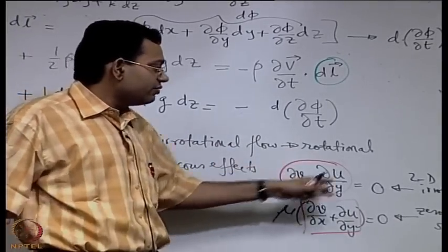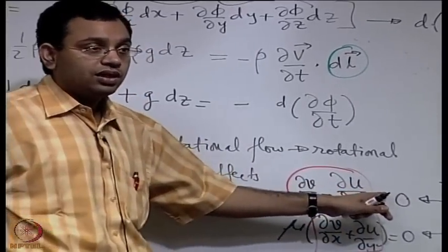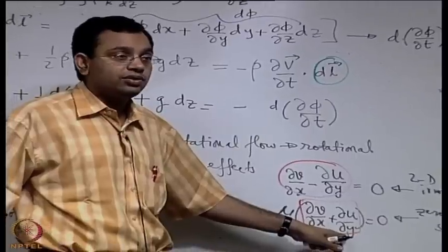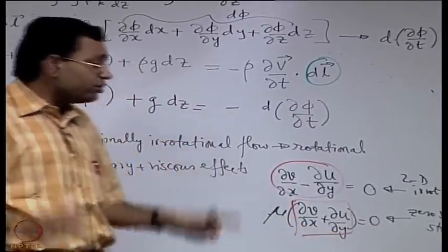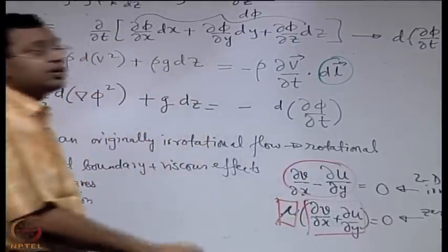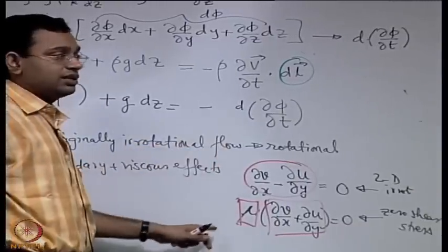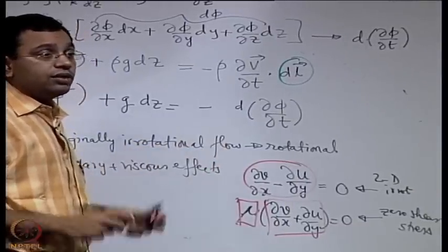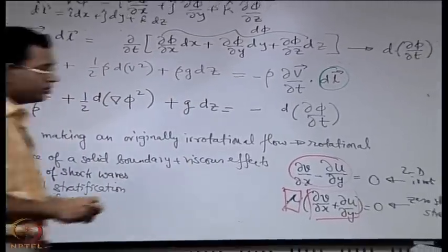In general, if you have an irrotational flow, so you have terms a minus b equal to 0, that does not ensure that a plus b equal to 0 until and unless a and b are individually 0, that is a very special case. So you are relying on what? You are relying on having mu identically equal to 0 to have inviscid and irrotational flow. Physically sometimes it is not a very absurd way of looking into things, though mathematically you cannot ensure that.